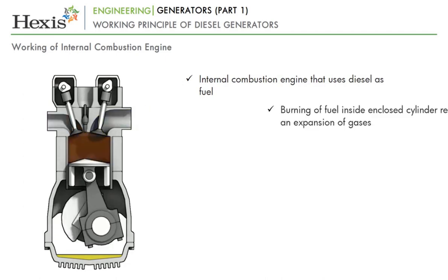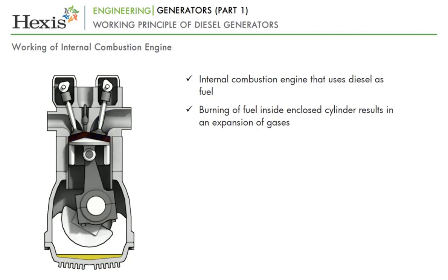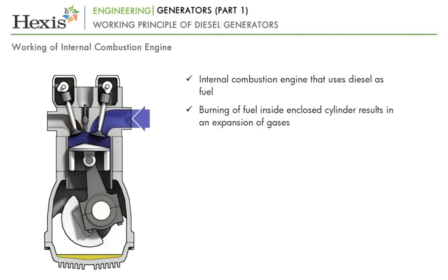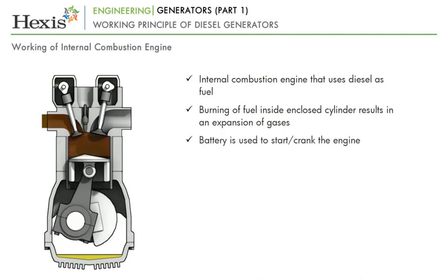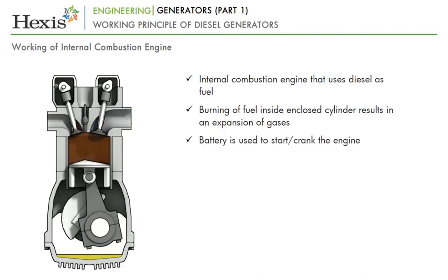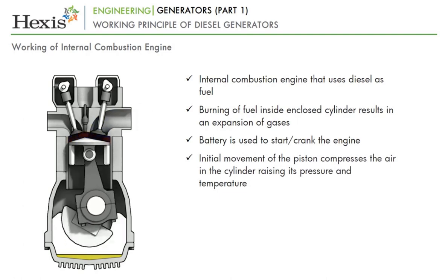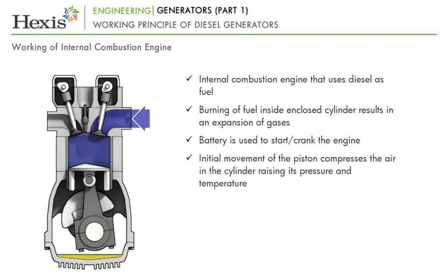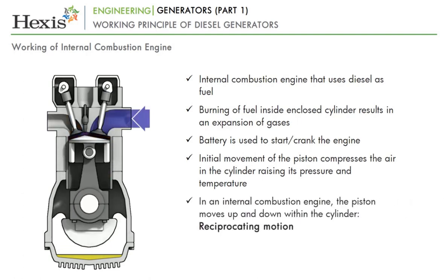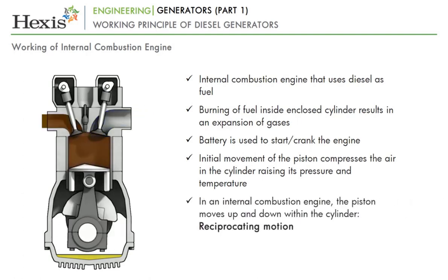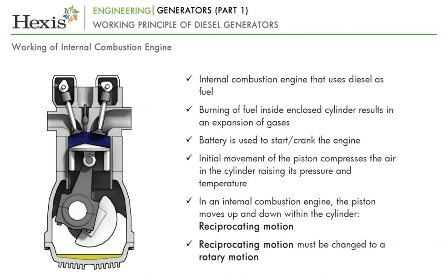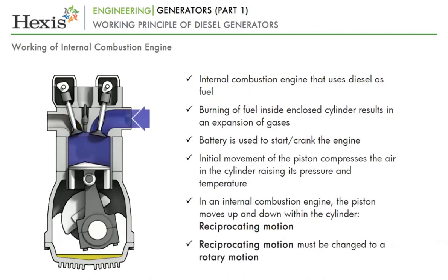We all know that burning of fuel inside an enclosed cylinder results in an expansion of gases. In a diesel engine, a battery is used to start or crank the engine. The initial movement of the piston compresses the air in the cylinder, raising its pressure and temperature. In an internal combustion engine, the piston moves up and down within the cylinder. This is known as reciprocating motion, which must be changed to a rotary motion.